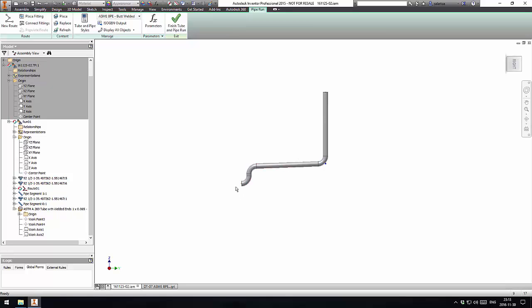Just imagine you have a pump at one end and you're pumping, and then by the time you get to the vessel, to the stainless vessels, or wherever your points of use are going to be, you cannot just keep rising. So you're going to have to create a high point in the middle and then go down in the other direction. So it'll drain in both directions, if you know what I mean. But Inventor doesn't permit this, and for that you need to work with tubing with bends. But that's another viable solution.